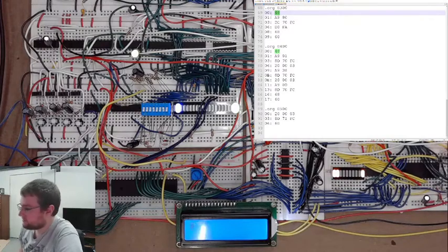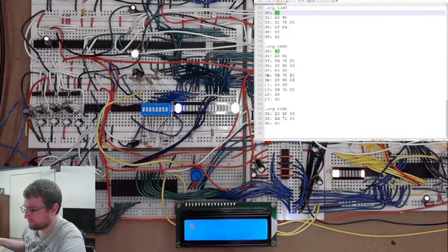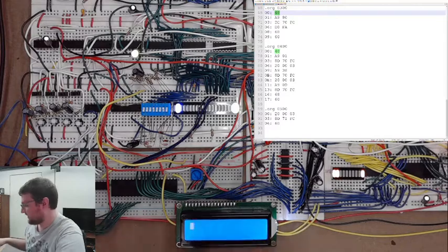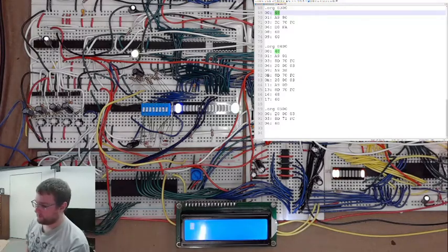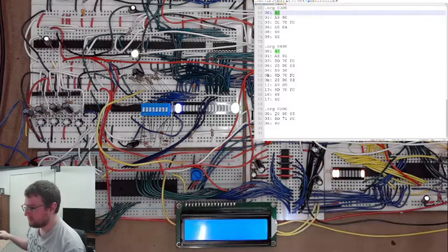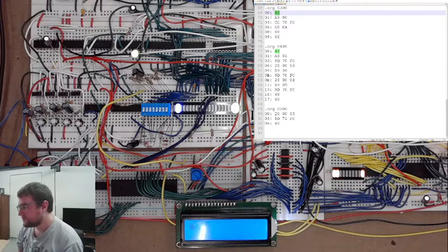But I don't think it'll change much, because when I add the capacitors, it starts working okay. Which would mean that it's basically having trouble getting the power to where it needs to go. So it's just in individual parts of the board or individual chips.